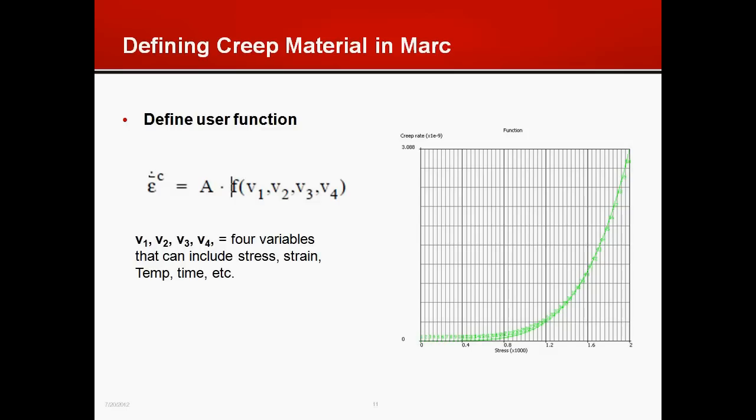And so to facilitate this, Marc provides another method of input, which also uses the tables, but instead of actually reading the tabular data, you can provide an equation for this multidimensional function. So Marc would then use this function instead of the discretized data. You can define any type of function as long as it is continuous, which means there are no step functions or discontinuities. And I will show these options during the demo in just a few minutes.